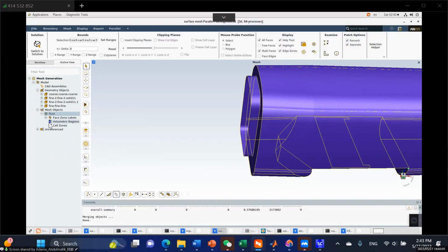So what I want to do is to right click on these volumetric regions because I want to divide these regions, what is solid and what should be fluid. Inside the computational domain, it's supposed to be fluid, it's supposed to be air, right? Then the train itself should be a solid body. So I'm going to separate them. The system is going to identify if this is a solid or a fluid region. So I'm going to right click and I'll come to compute.